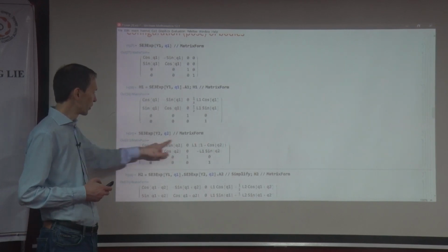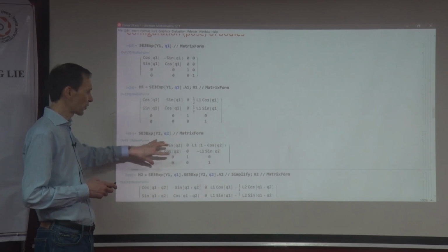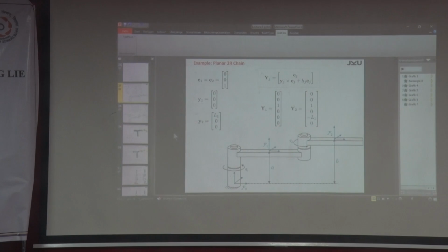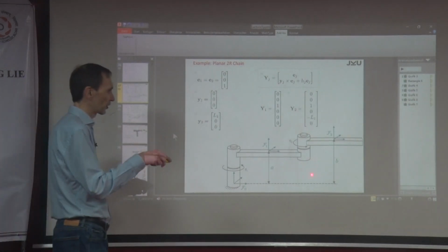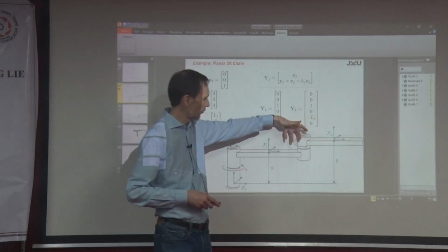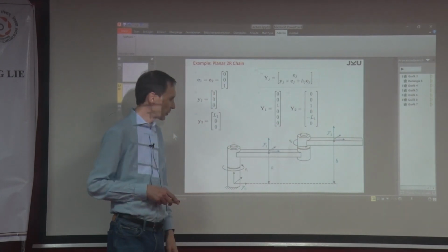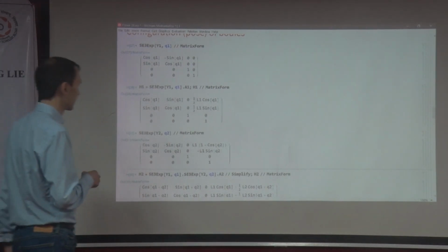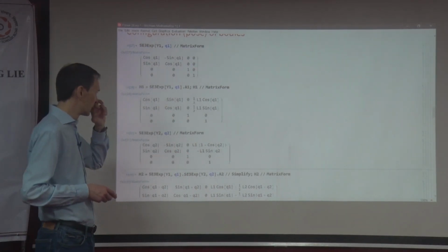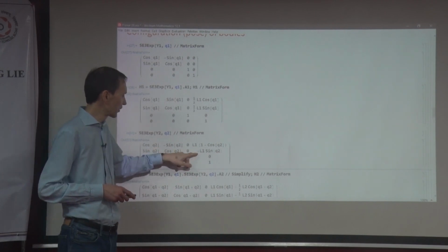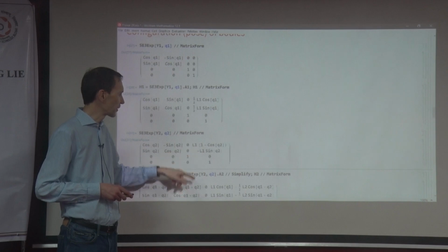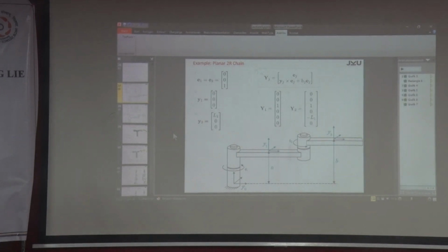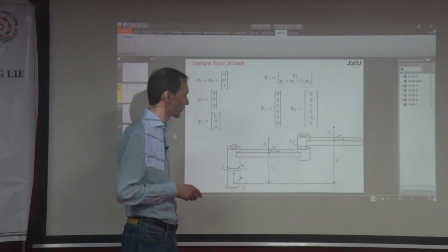So first of all, look at the rotation matrix. It gives you a rotation about the z-axis. That should be okay, I guess, because the second joint again is rotating about the vertical axis. Now, what is the position point, the translation? That part is interesting. Maybe look at the easy one. The y component is minus L1 sine of the angle.